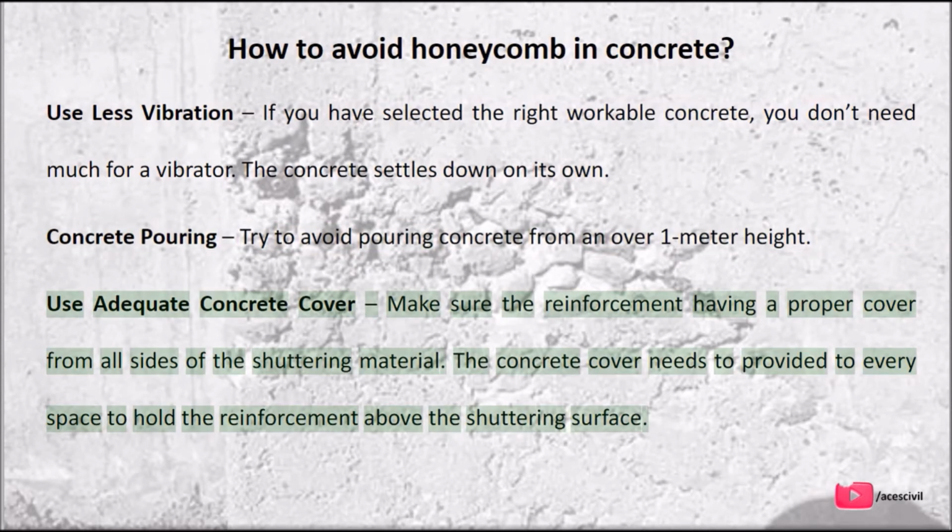Use adequate concrete cover. Make sure the reinforcement has a proper cover from all sides of the shuttering material. The concrete cover needs to be provided to every space to hold the reinforcement above the shuttering surface.